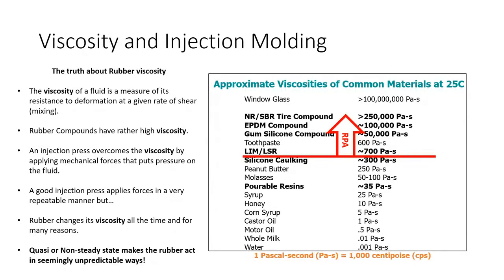And as we go across this line, and I've got this arrow, the rubber process analyzer, the RPA, is really necessary. It's got the motor and the die system figured out for measuring these specific high viscosities. And right around 500 Pascal seconds in viscosity, measured, by the way, and I should probably footnote this, all these are measured at 10 reciprocal seconds. As we know, rubber is shear dependent. So all these numbers are the 10 reciprocal second shear rate numbers that we see. It'd be a good thing to add up here.